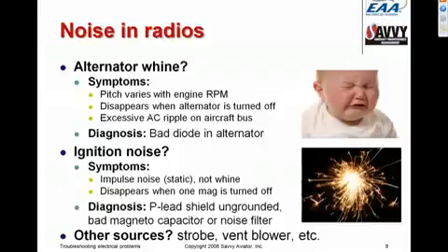In my airplane, because it's a twin, there are 4 mags, and when I first started hearing this impulse noise in my radios, I cycled in flight. I cycled 1 mag off at a time until I discovered that when I turned the right engine's left mag off, the noise went away. And that confirmed to me that, first of all, it was ignition noise, and second of all, that it was associated with the left mag on the right engine, which is the big first step to troubleshooting this problem.